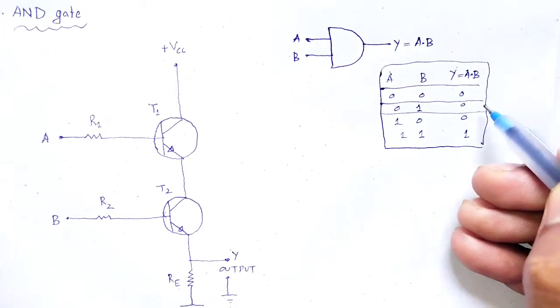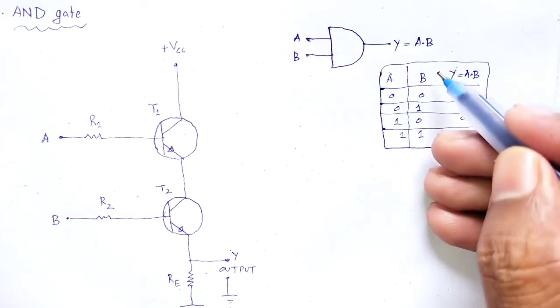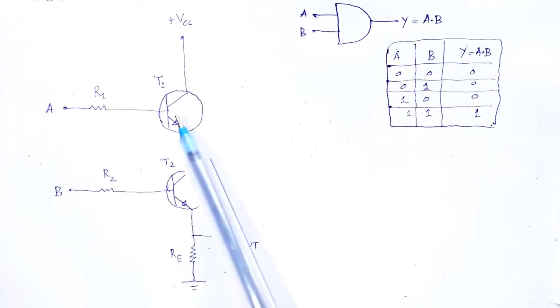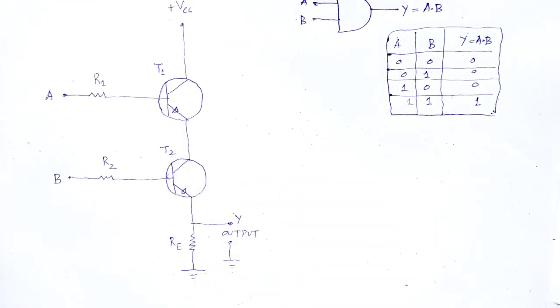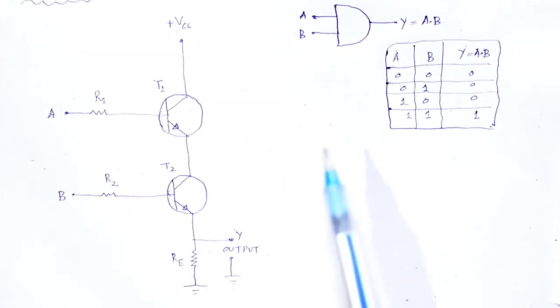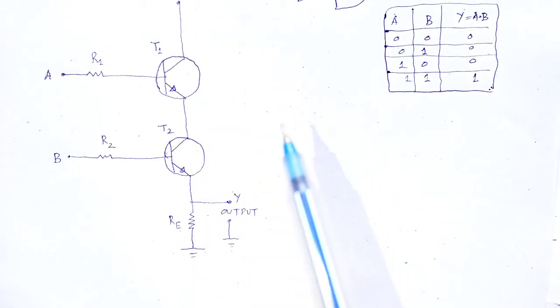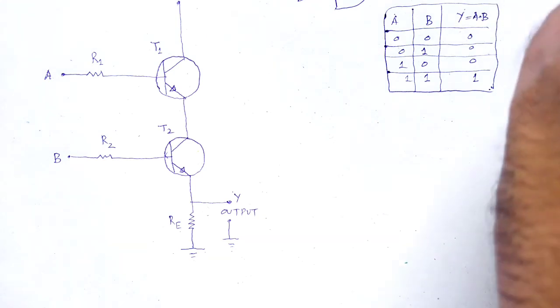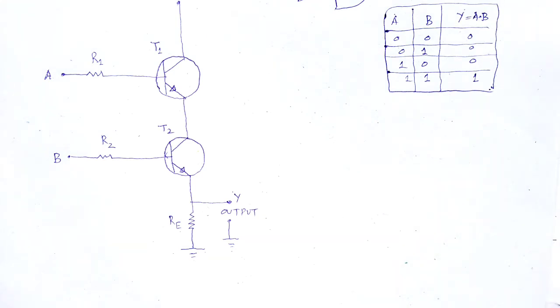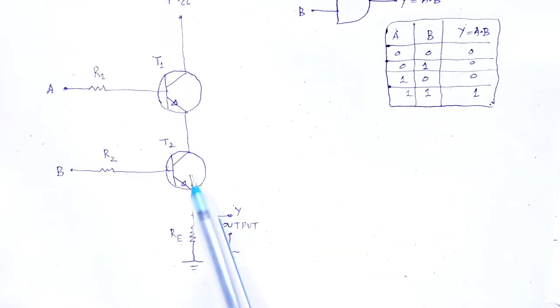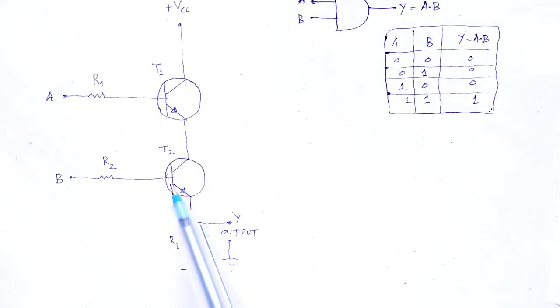These cases can be easily understood by taking transistor. So we have two transistors T1 and T2. These two transistors are connected with each other in series to show AND gate, and the transistors are just like that of a switch. So when we have the possible situation 0 0, the inputs of the first and second transistors are 0.